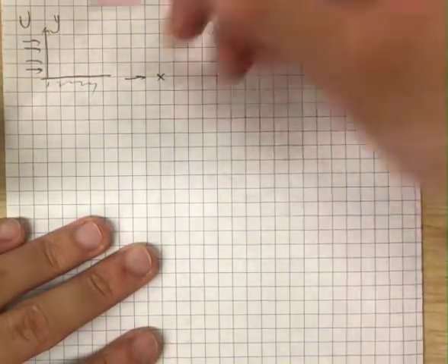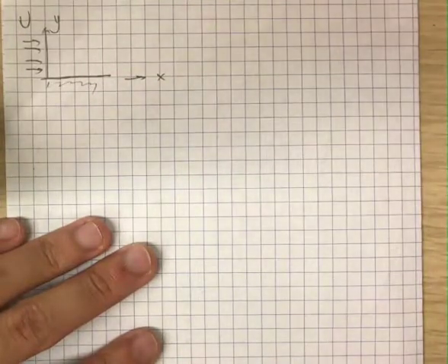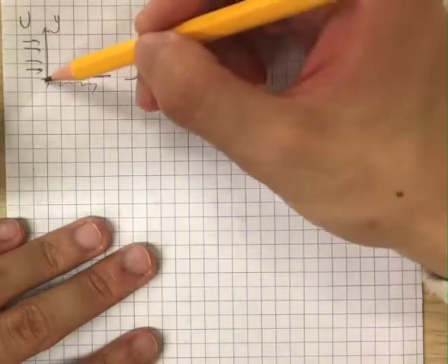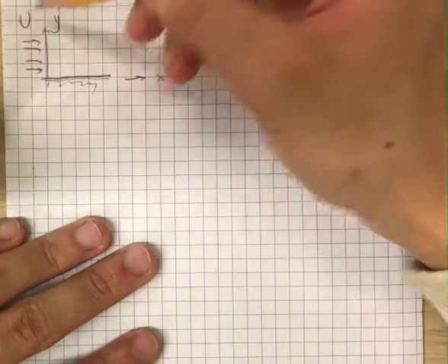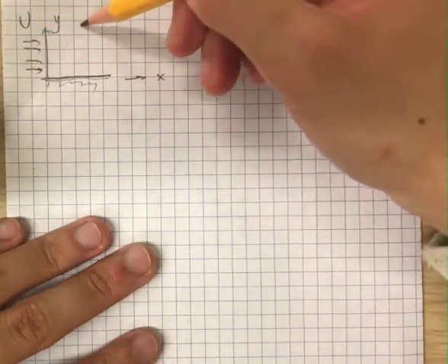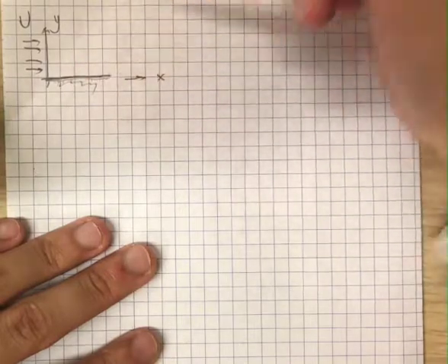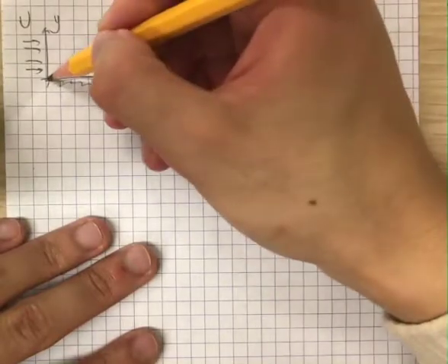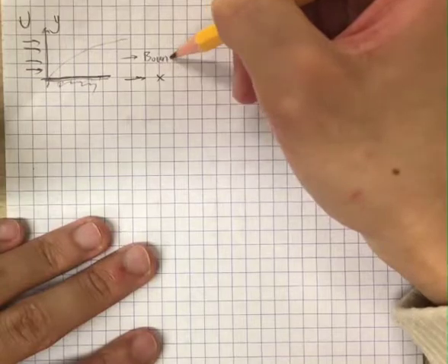At a place that is very near the boundary, we would expect the velocity there to be 0 because of the no-slip condition. But what will the velocity be like at a place that is very far away from the x-axis? It will be nearly u, because I'm very far away from the solid boundary, right? So we can define a layer which we call the boundary layer.